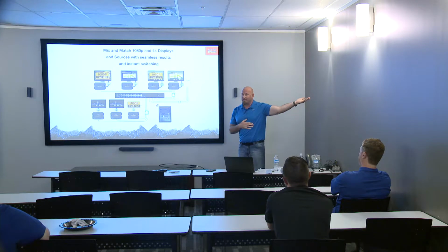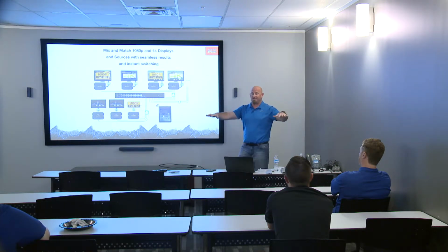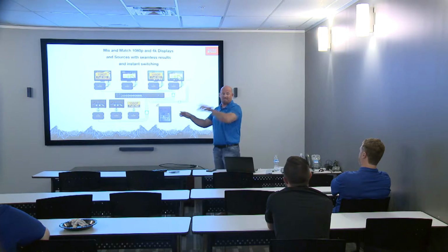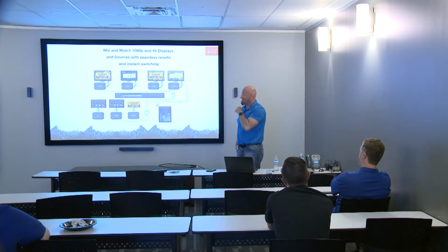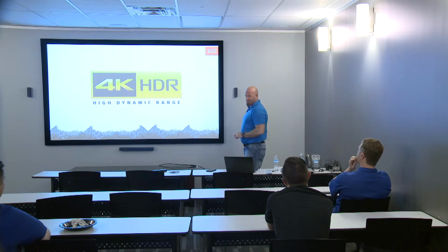Dad's watching 4K in the living room, someone turns something on in the kitchen, and with a standard black box matrix, it will go to the lowest common denominator EDID and now send 1080p to the living room TV and 1080p to the kitchen TV. With Just Add Power, that's not a problem. The receiver does the scaling.